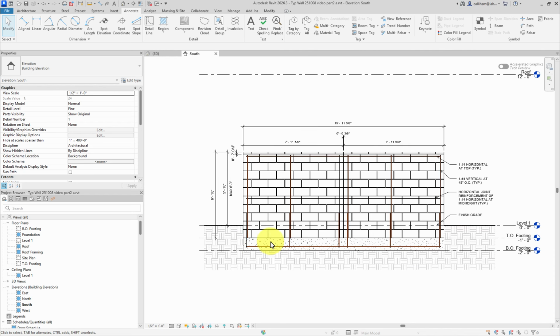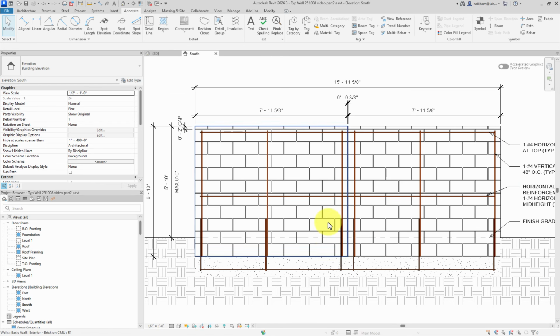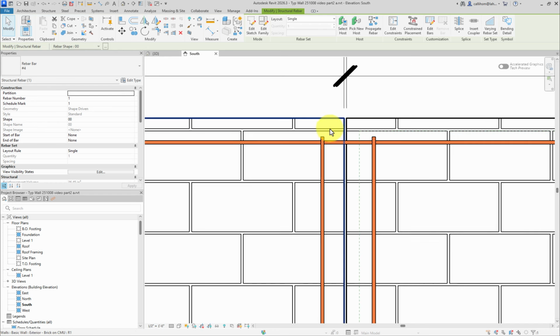There's one important thing that I wasn't quite thinking through and didn't quite realize, and that's that our rebar is running continuous across our control joint, and that's not something that happens realistically, right? So our footing is one continuous piece running all the way across, and I made this rebar as my very first one. Then I copied it up to here and copied it up to here and said, oh, everything's great, this is all going well. We definitely cannot have rebar passing through and being exposed and then continuing like that, right?